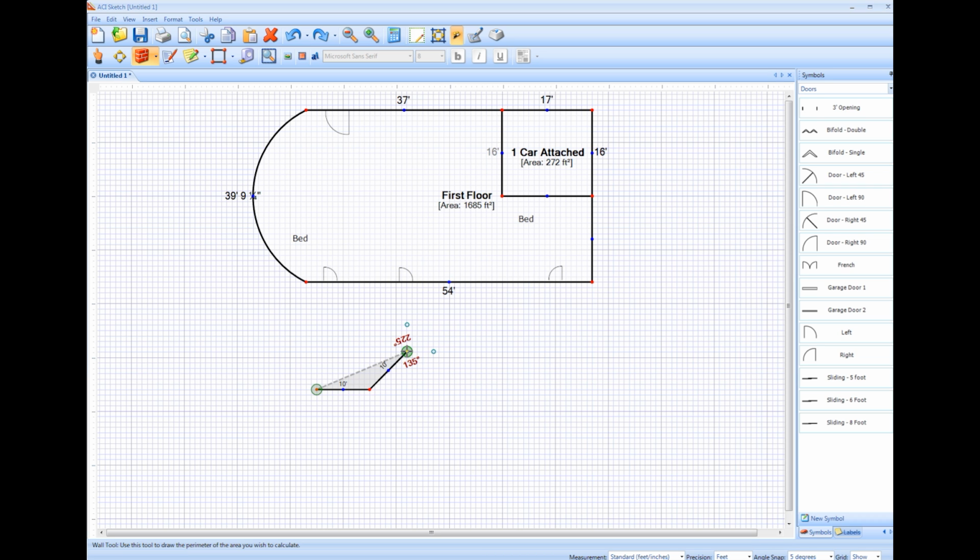Now, if I wanted to straighten that out and head right for 8 feet, I'm now headed in a direction of 45 degrees to the northeast there. So I have to bear right by 45 degrees to draw a quote-unquote straight wall. So if this is an 8-foot wall, I'm going to type 8, R on my keyboard to bear right, then 45 to say it is a wall going 45 degrees to the right of the direction I'm headed now. If I hit enter, I've got my flat angle there.